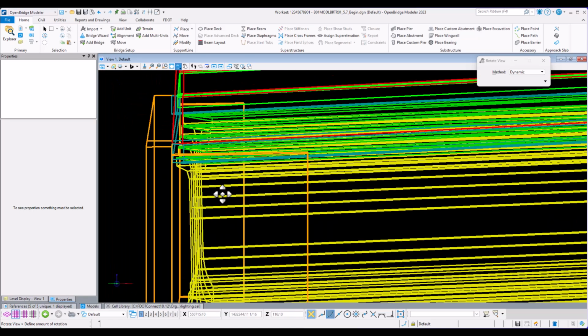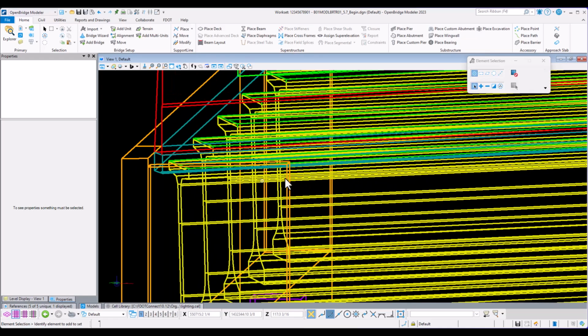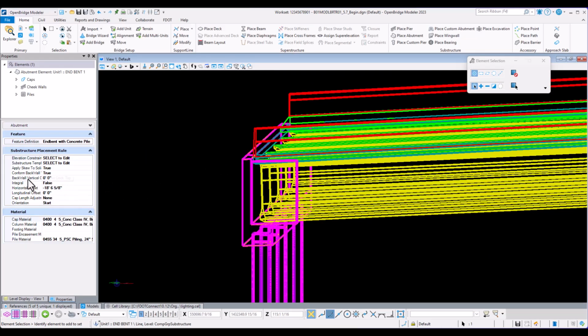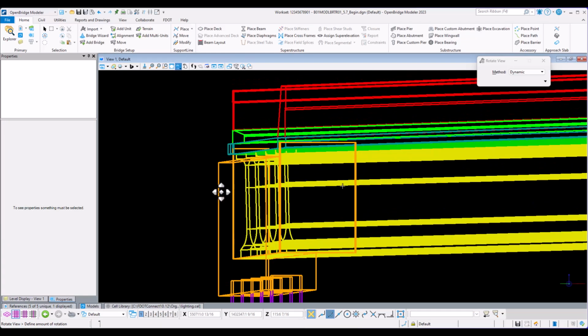That thing's going to be about 1 foot 3 3/4 below that to receive the approach slab. So we'll click on that and change this back wall vertical offset from top. We'll put negative 1 foot 3, and we'll just do 2.5 for this one here. And see how that drops that back wall down below the deck where we want it to be.